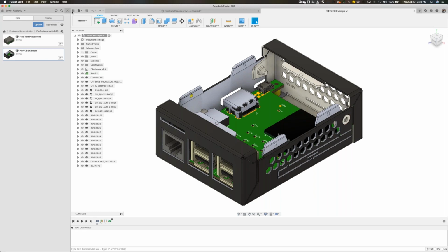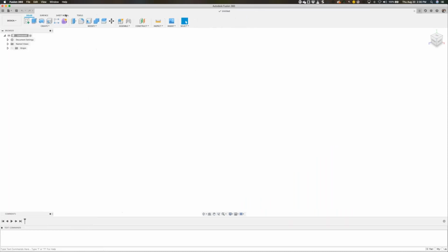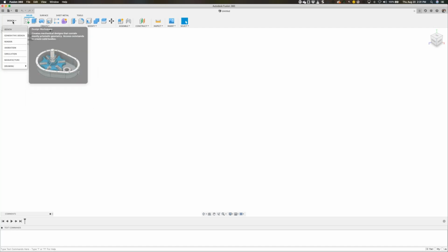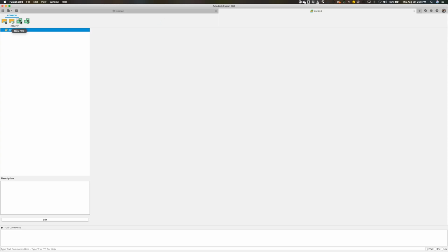Okay, that's not going to work. So first of all, let's show you how you access the electronics in Fusion 360. When you launch Fusion 360 for the first time, it looks like this. It takes you directly to the design workspace. You'll see the different workspaces available right here on the left-hand side. To access the electronic workspace, click on the File pull-down menu and select where it says Electronic Designs. This is going to bring you to what we call the electronic document.